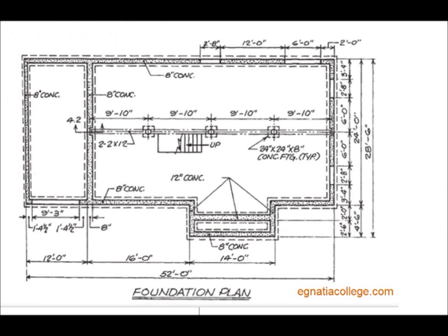When the concrete for the footings has hardened and the forms are removed, carpenters can begin erecting forms for concrete foundations, or masons can begin laying blocks or bricks for masonry foundations. Although the material differs, the drawings and their interpretation for each type of foundation are similar. The outside surface of the foundation wall is laid out using previously constructed batter boards. Then the forms are erected or the masonry units are laid to these lines.